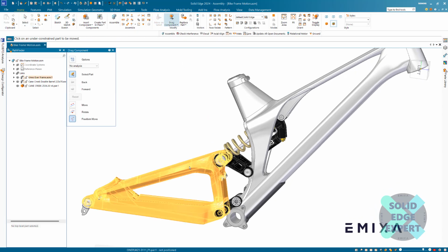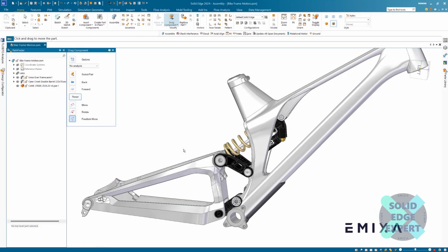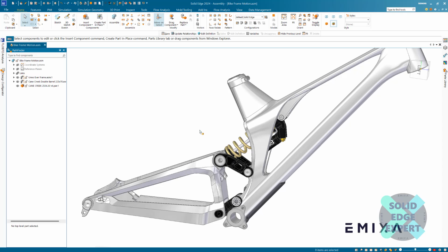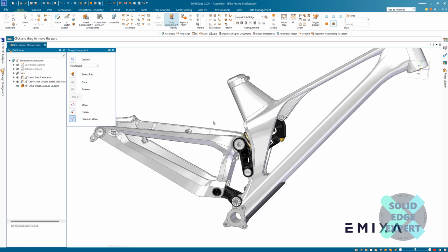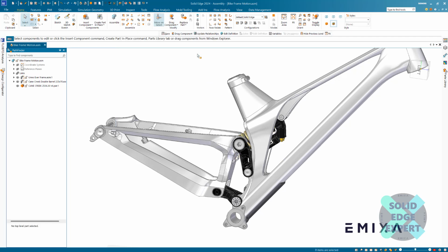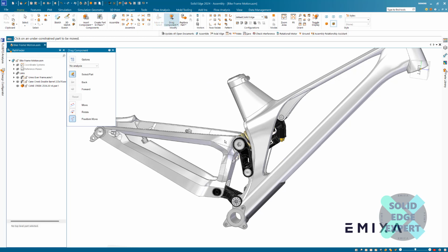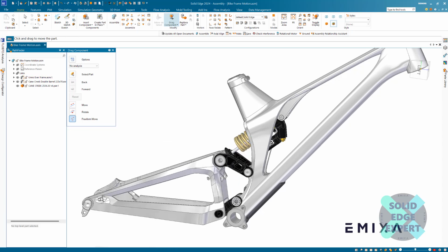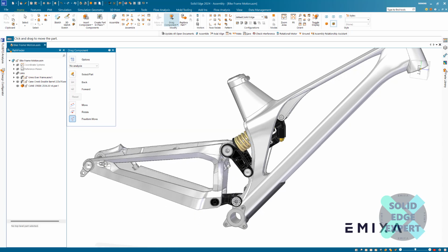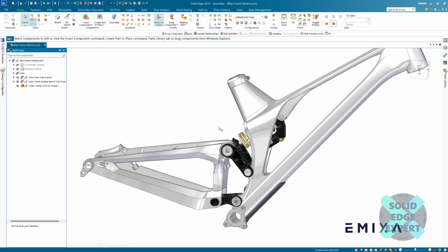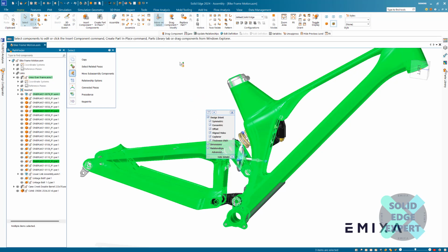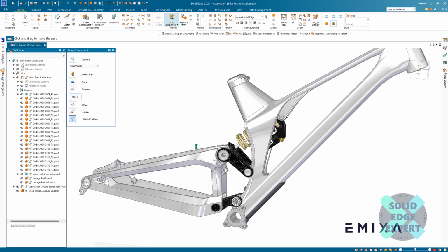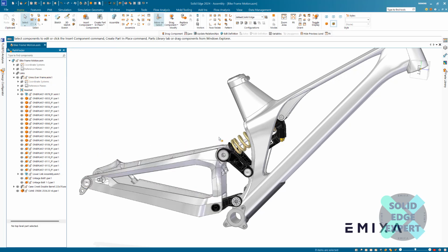That's nice. Let's go back to drag. We can see if we drag that, that's the maximum on there. Remember, we need to do the update to get that spring. And let's go and drag that back up again. Choose drag component. Let's go and take that all the way to its limit, and let's do an update on that spring. You will find sometimes if you go all the way from one end to another, that's not going to update. So doing that in an interim position, you'll find it's more likely to update if we take it into an interim position rather than going all the way. So let's try and get that updating on there.